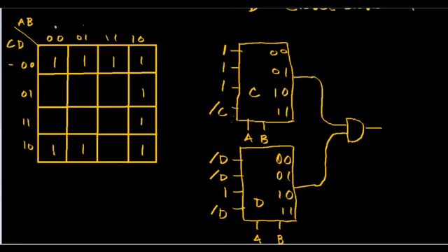Okay, and let's just test two random spots. Let's pick this spot and test it out. This should give us a false statement. This should not output a 1 out here. So we'll look at C first. A and B are 0, 1, so we're dealing with this line of logic here.